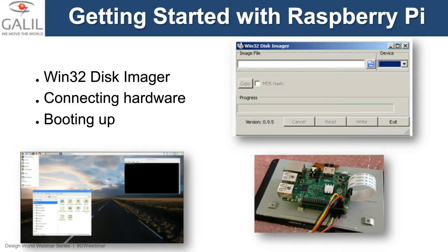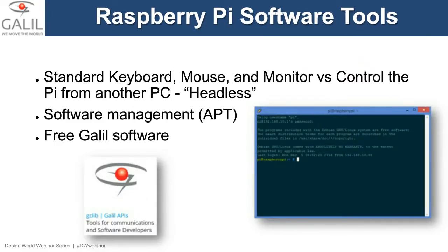So there's really two main ways that you can interact with the Raspberry Pi. The first one, as I'd mentioned, is through this keyboard and mouse. The second one, which is a little bit more abstract, is called headless control. Basically, all you have connected to the Raspberry Pi is the power supply and an Ethernet cable. And if you have an IP address assigned, you can now connect directly over the Ethernet network with something called SSH, or Secure Shell.